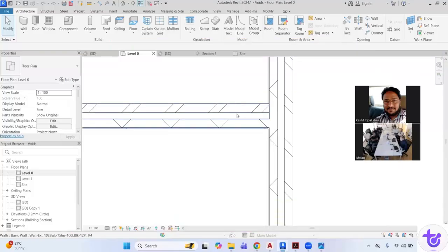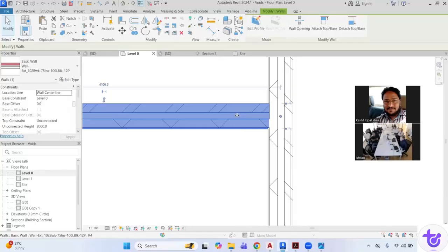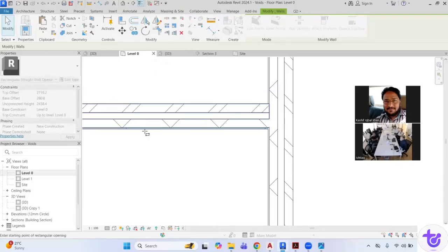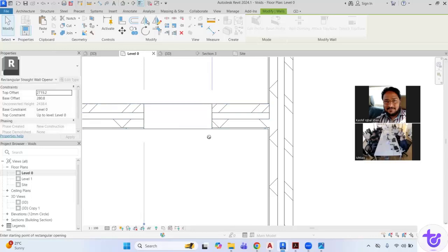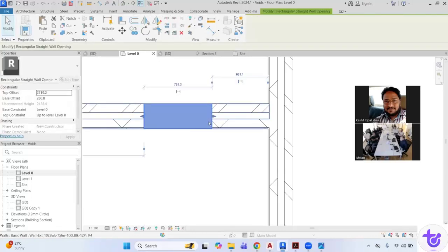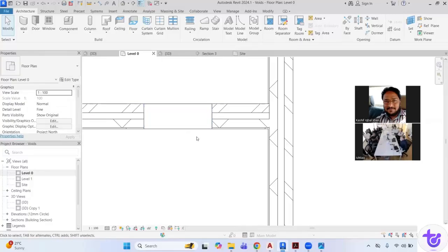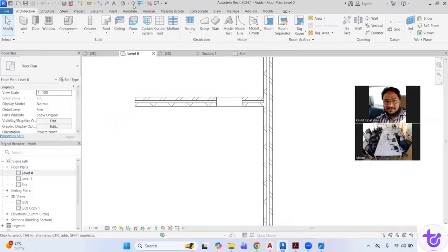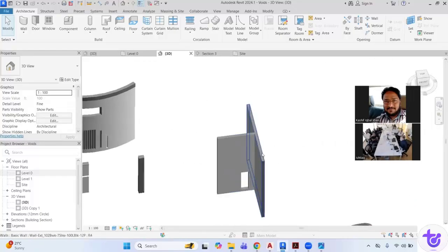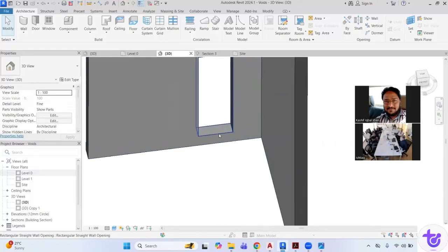No, you want the door opening or any opening by the profile? If in case it is a normal wall opening like that, we cannot get a schedule. You want this opening? No, this one we will provide. Then we are not getting a schedule also. Yeah, it will actually update the schedule. If there's an opening in the wall, this will reduce the quantity of the plaster.